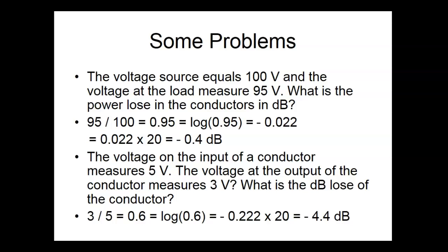With AC, we can get a pretty good idea of what the current is by the strength of the magnetic field. So with AC, we have the ability to buy what we call clamp-on ammeters. Have you ever seen a clamp-on ammeter? Well, is it measuring current? No. It's measuring the strength of the magnetic field being created by the current. So you're not actually physically measuring the current. And you can't put it across 2 wires, because as soon as you put it across 2 wires, they cancel each other out. And you can loop them, by the way. If it's AC and you got enough slack, you can loop them. So if you loop it twice, then your meter, if it measures 500 milliamps, it'll measure 1 amp. And you just have to divide it by how many times you loop it.